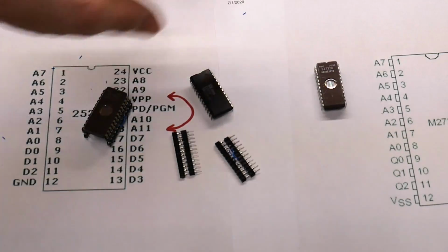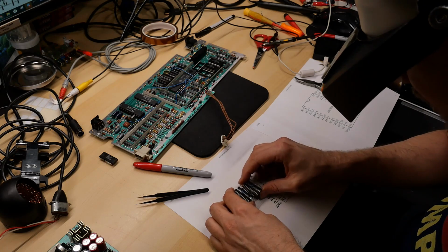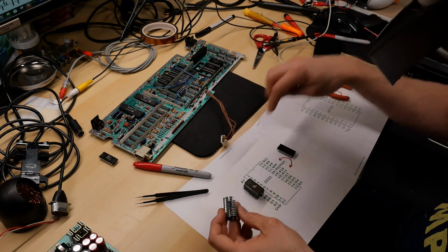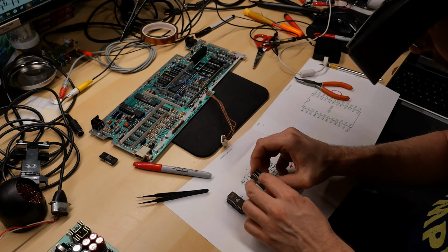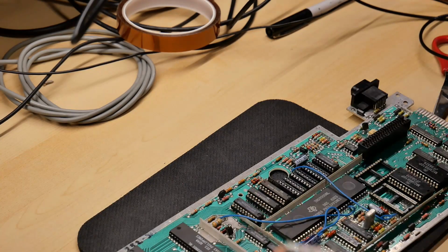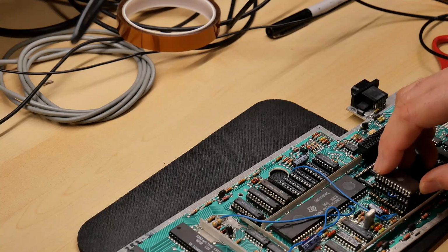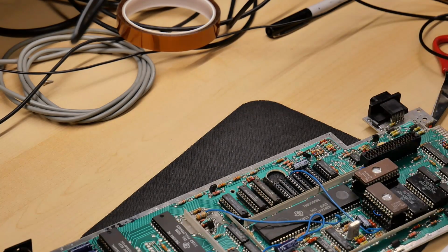So I'm going to put this one on here, and we're going to install them in the computer and see if it boots. You just want to make sure that it's the correct 2 pins that are swapped around. So I'm looking at the picture here, the notch is up at the top, and the notch is up at the top on these, and it's these 2 pins. So that is correct. Now, unfortunately, I'm not sure which of these EEPROMs is which when it comes to on the board. So I'm just going to install them in here and see what happens. Now it's a hilarious stack of chips, but hopefully if this gets it working, then we're golden.